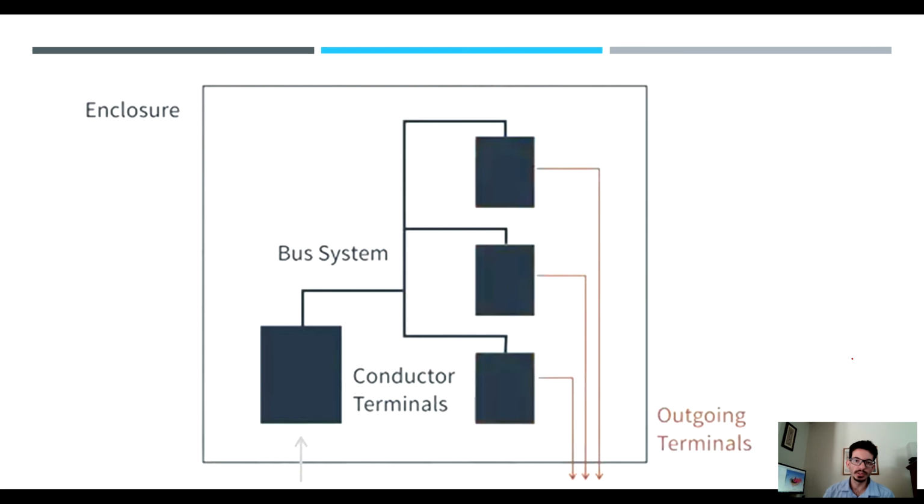So a panel board usually looks like this. In this picture, you're gonna see that we have all these parts where this is your incoming power. In our example, we had 240 volts. And then we can either here have fuses and breakers, probably very common to have relays, and then we distribute to all the other things that we need.